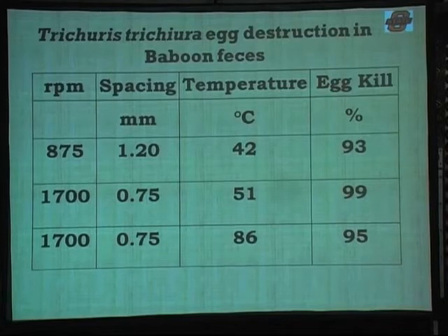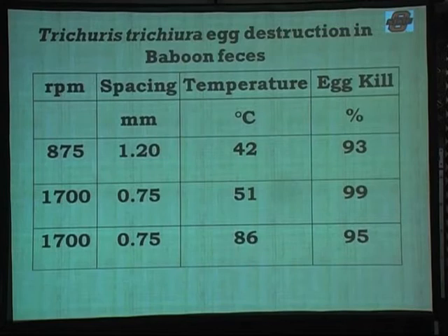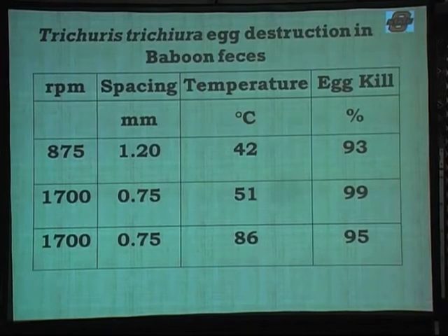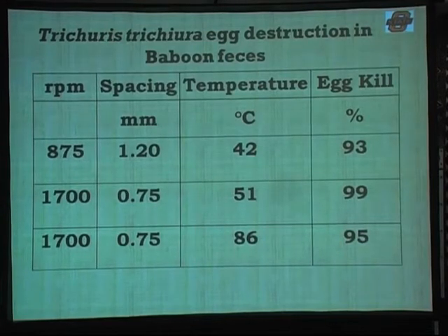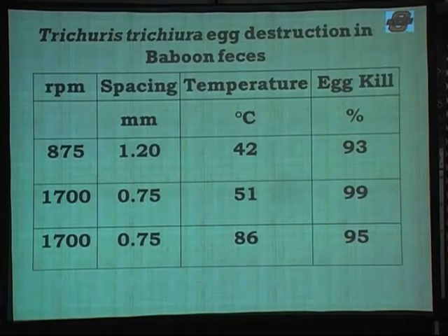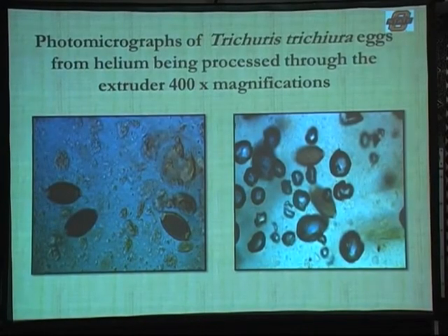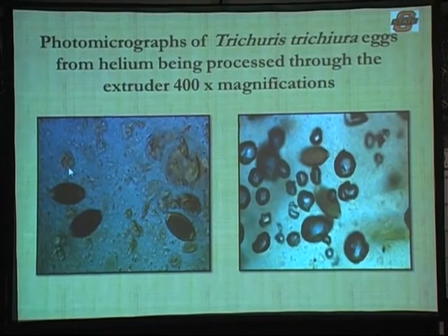But when we took samples out and then refloated, recounted the eggs that were left, we were able to determine greater than 90% destruction of parasite eggs, even in that case. And the primary mechanism here should be the shear stress, basically ripping them apart as they're going through this system. And there's a couple of pictures of some of them after they've come out.